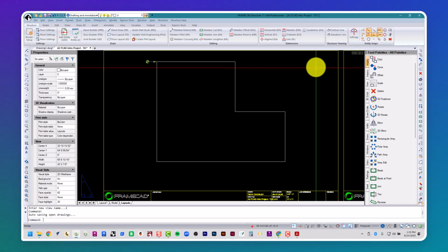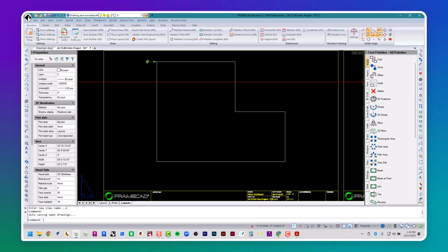This polyline will represent the heel location of the trusses and be coded as support line. We also will learn how to add and code roof lines representing the eaves overhang. Note, wall panels, trusses, and joists all have different properties and different engineering requirements. Coding informs the FrameCAD structure software of the function of the line you are drawing and therefore what intelligence should be applied to it.